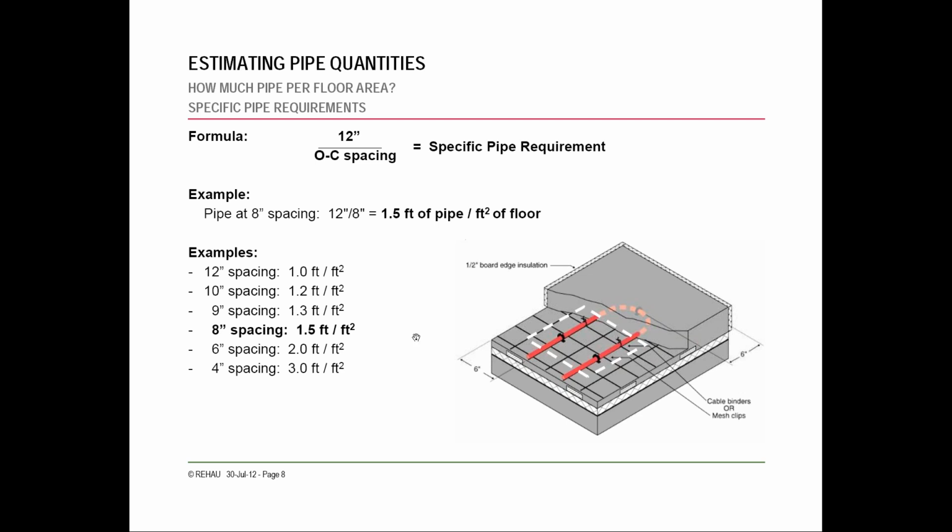When you're doing joist-based installation, if you have standard 16-inch joists, you're going to do 2 runs per joist space, so you're going to be looking at 8-inch spacing. And then depending on the areas or stairs or whatnot, you might go down to 4 or 6 inch spacing.